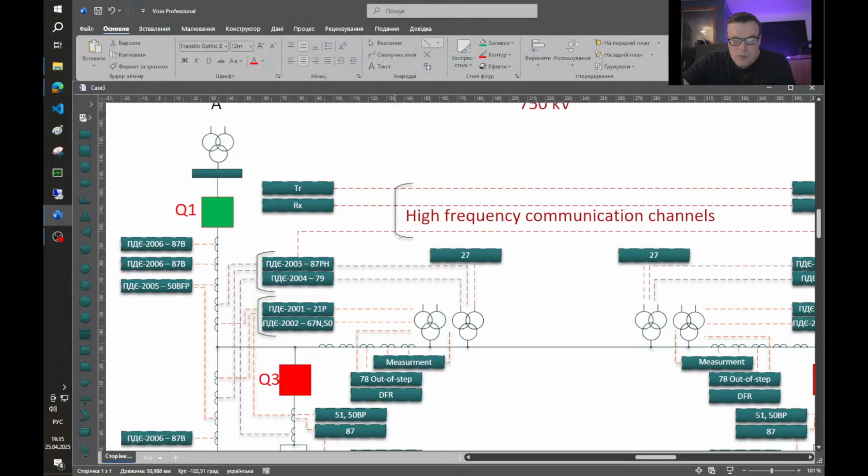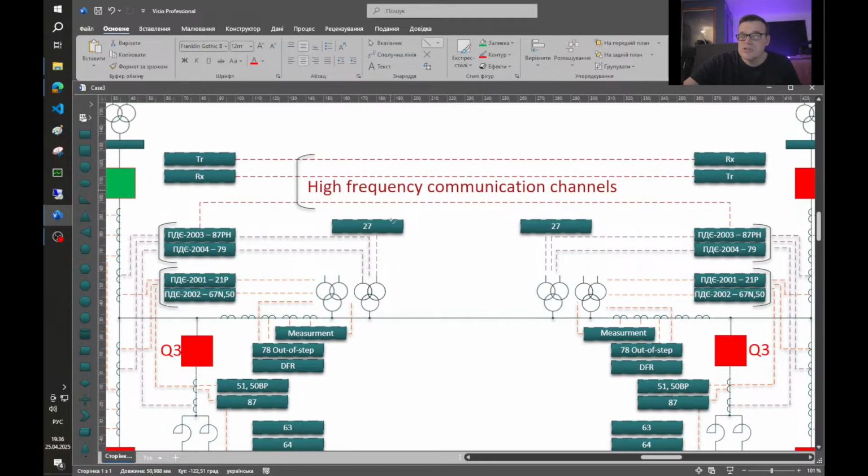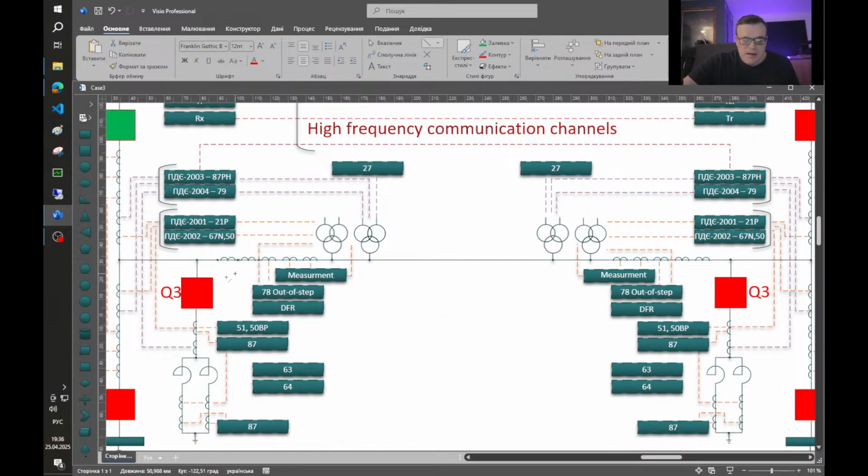I believe that one of the main protections is this overvoltage protection, and I forgot to add some words about it. It usually has two stages, and the first stage is when voltage is like 15% higher than rated voltage, and with zero time it usually closes this circuit breaker if before the event the line worked without a shunt reactor.